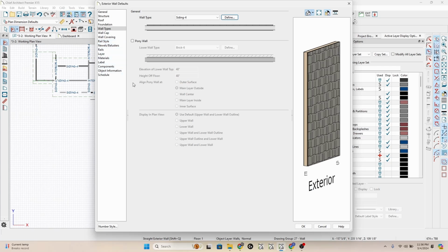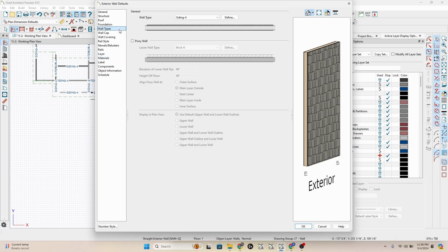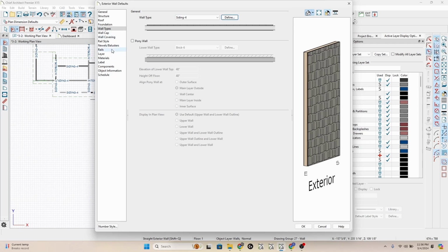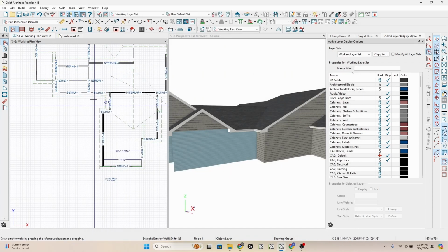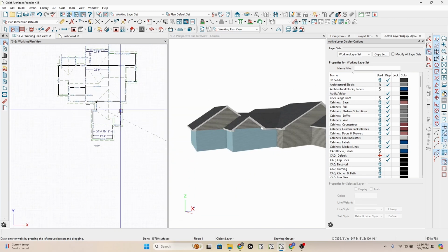So as I was saying, there are multiple ways to control defaults. In your exterior wall default, the default is that the wall will have granite gray. But there's also the default of the default wall type. But this is being overridden by the wall default here. Okay, so let's set this up here.